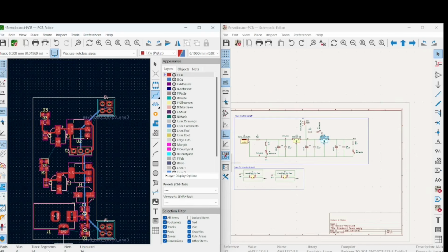On the bottom, you can see it lists the pads, number of pads, vias, track segments that you have used, the nets, and the unrouted connections. So now it's showing me 16 unrouted connections. So I'm assuming it's the ground connection. So let's move further. Maximize this window and let's work on the copper pour. So we will do a ground copper pour.